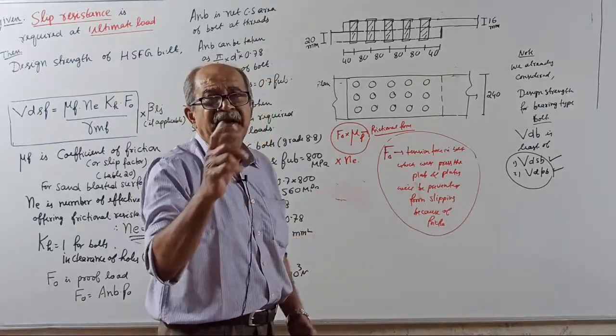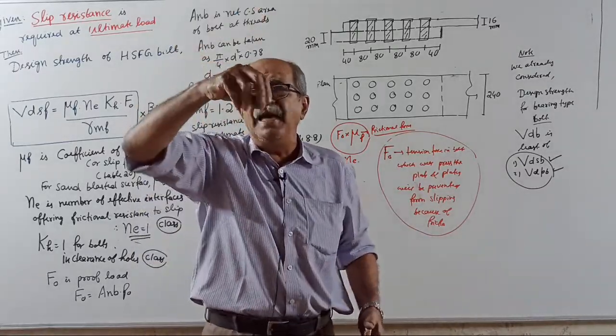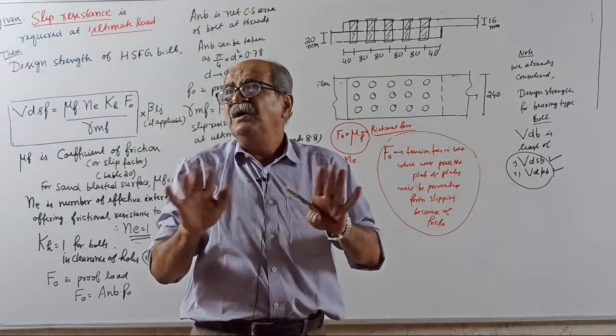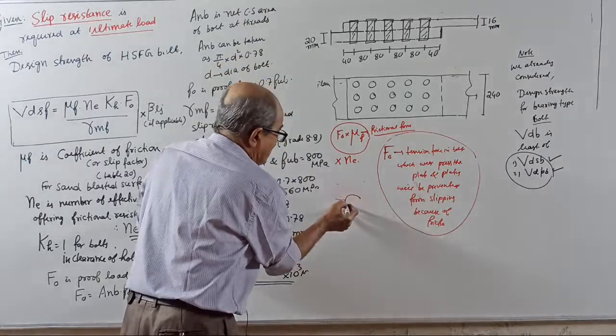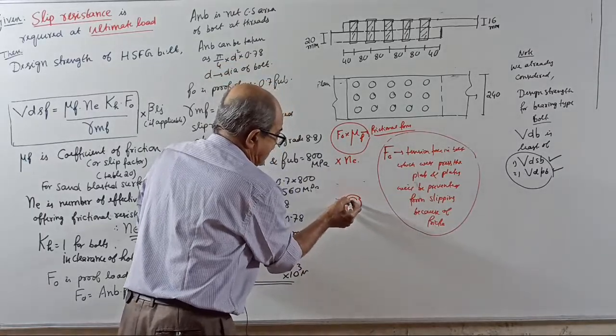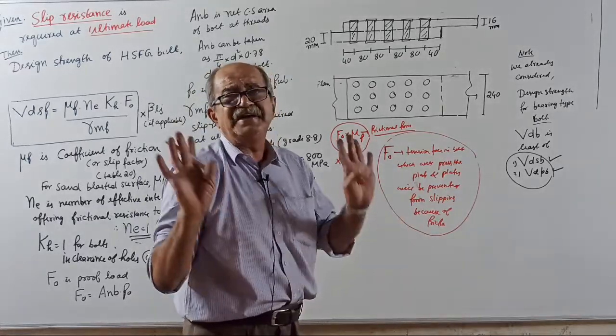But one correction. If the bolts are perfectly placed, there is no question of slots. If the plate bolt hole is like this and the bolt is correctly this way, it is the ideal case, then there is no reduction.